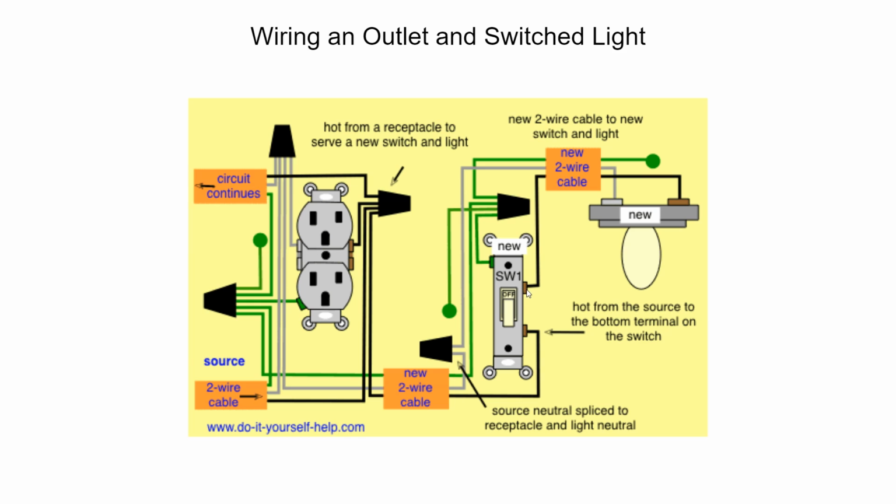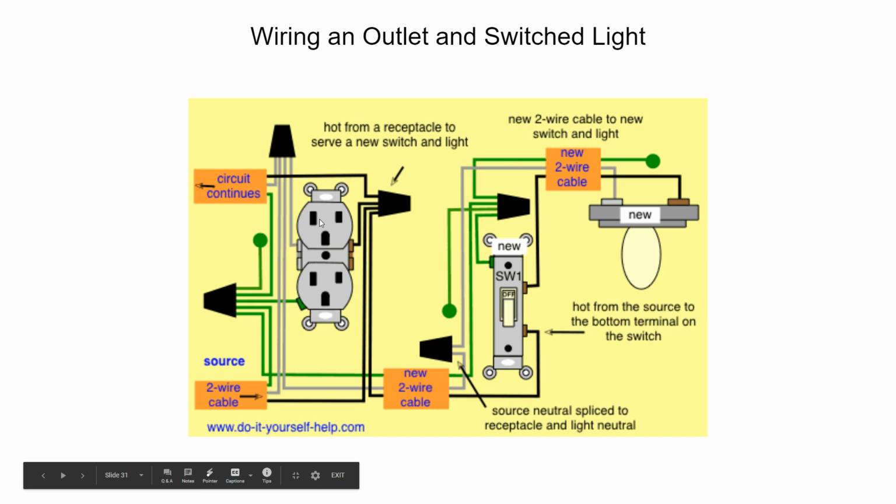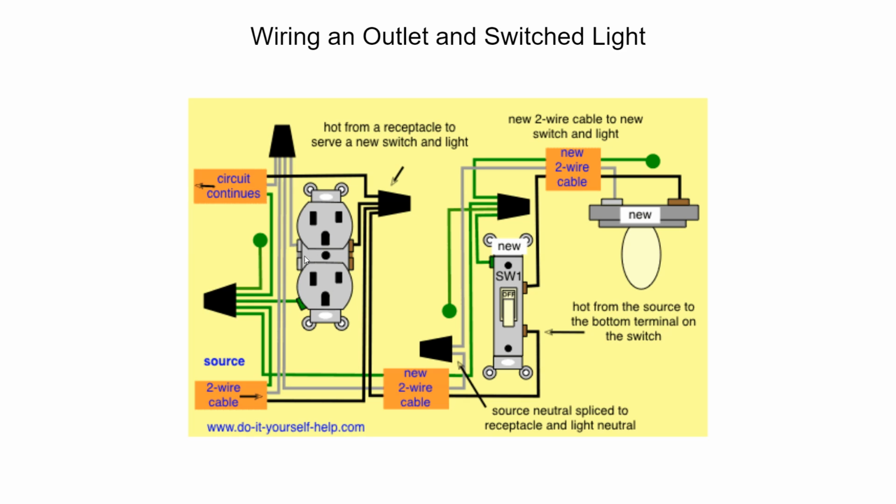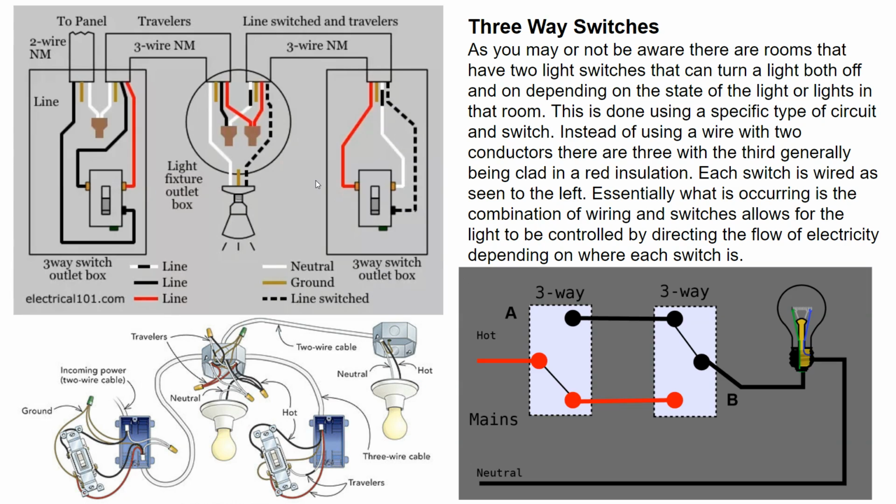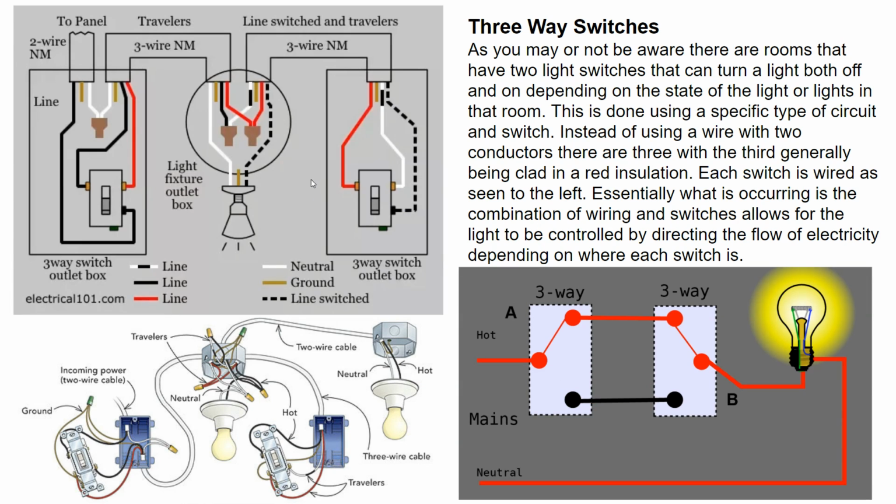Then we go to our second brass screw, which is connected to that. So this is now hot. And then we connect everything up in the box that our light's in. So we come in, connect here. We're using wire nuts instead of connecting to here. That's fine, you can do either or. Then black goes to our switch. In our next box, our white wire carries through that box and connects to the neutral or the white wire from our light, and the light hot goes to the switch. That's everything on that. I just want you to be familiar with this a little bit.